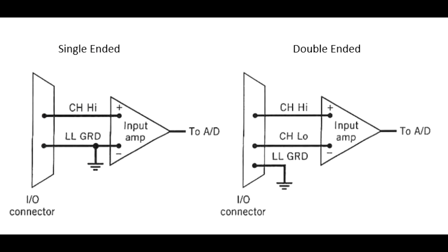Single-ended input is when you only have one signal line that is measured relative to the ground. As such, this is generally done to reduce the number of wires needed to measure the sensors. The downside of doing this is that the signal is very susceptible to EMI noise, which causes a larger signal compared to the resolution. Single-ended connections are only suitable when all the analog signals are made to be relative to a common ground point. This is because different ground points have different voltage values, which can distort the data.